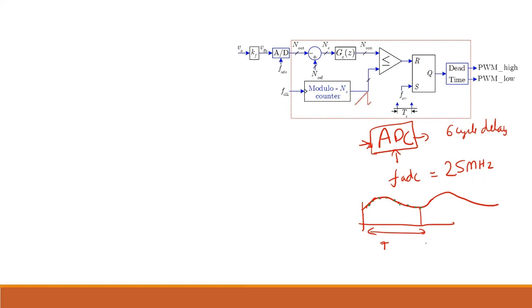That depends on FPWM. This FPWM signal comes over here, so this sample I will choose for my controlling. But all these samples the ADC is taking. The clock to the ADC is this clock: there's one clock here, here, here, etc. These are the clocks for the sampling of the ADC. So the ADC is continuously on, continuously taking samples. But which sample I am choosing, that is my FPWM.